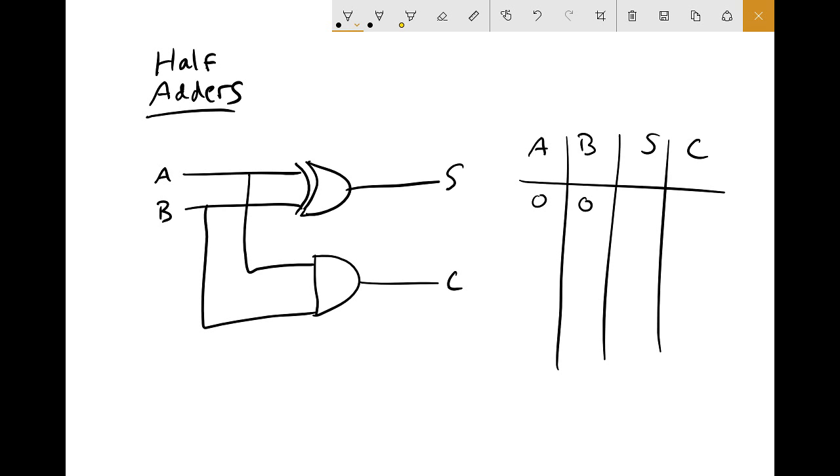Let's take our same combination of two bits. Logically, what we produce with XOR is the following. And that means that exclusively one of them is true, and only that will be true. The carry bit is just an AND, which we saw earlier.